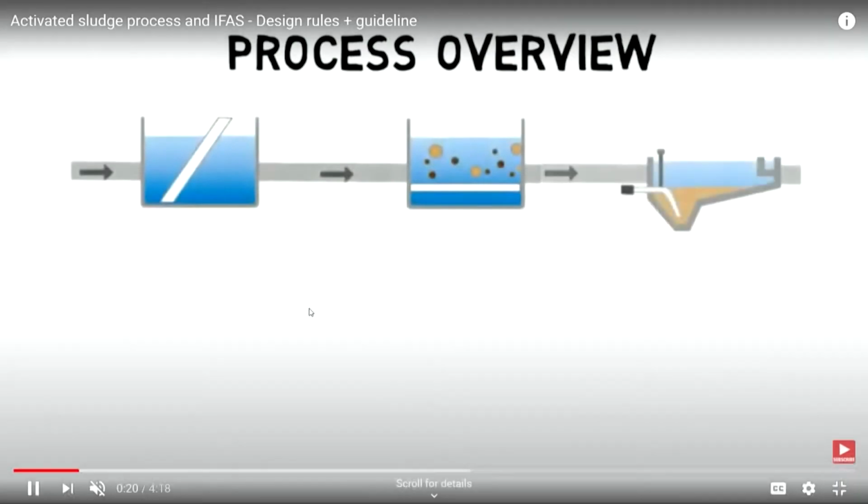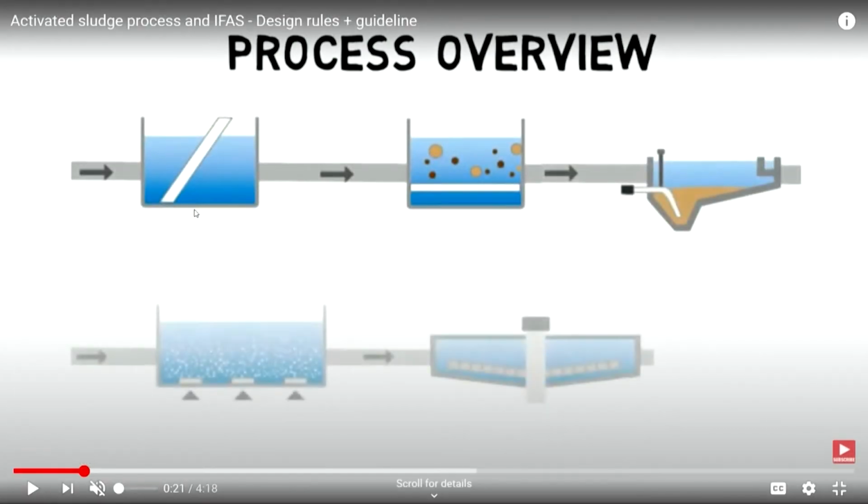So, process, what do we have? We have the grit chamber, right, or the screens, pardon me, coarse particles, rags and such, then the primary sedimentation basin, right, grit removal, primary sedimentation basin, and then we have mostly only the suspended matter. And here, I hope you can see the arrow, we have the biological process where air is provided, microbes are coming into the picture, that is why the biological process, and then the secondary clarifier or secondary sedimentation tank, let us say, right.